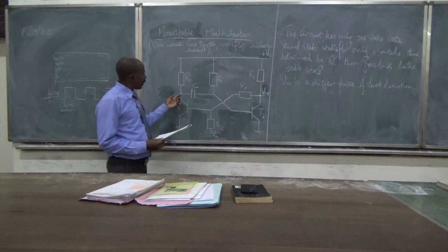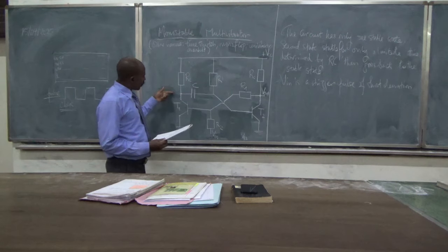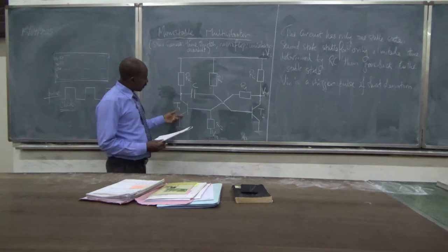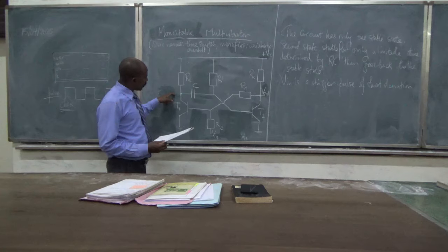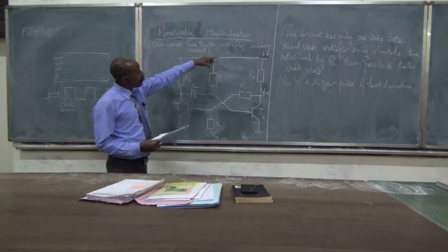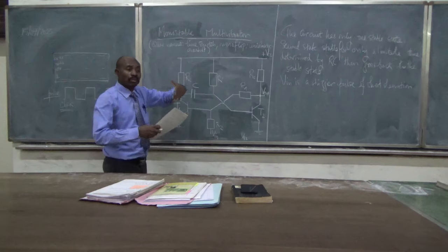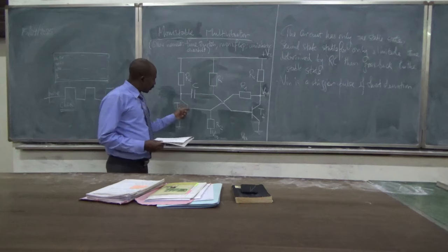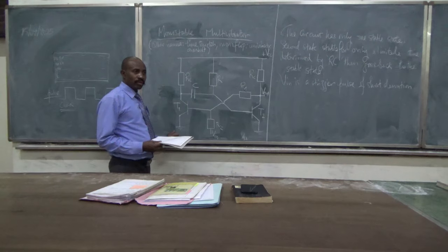then this one which was here, which was VCC, once you bias it and now there is conduction, then what you are getting here as VCE1, the value of positive VCC, now goes down to 0 because everything conducts through the transistor to the ground.